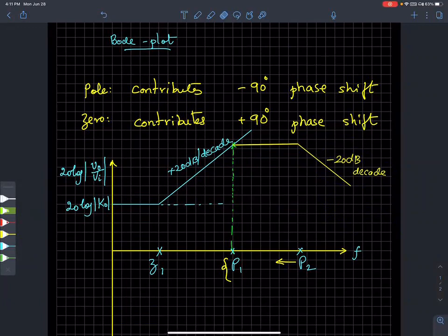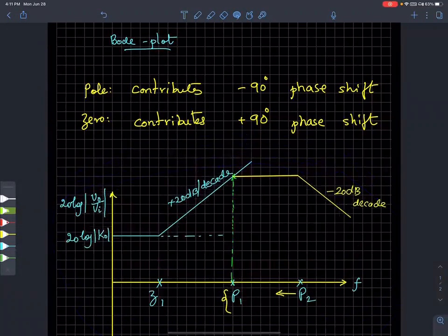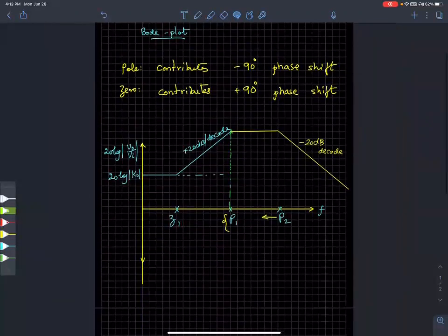Everybody with me? So the idea with magnitude response, or the pole and the zero behavior or effect on magnitude, is that it continues indefinitely. It does not end. In other words, this effect continues as long as you continue to increase the frequency; the magnitude continues to drop. Okay, questions please, questions so far?